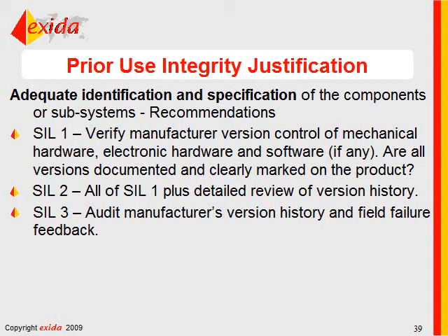What happens if you've been using a particular product for 5 years and you've got 1,000 of them out in the field and they've really worked well? And you've done good record keeping and you know they've worked well and they seem to be a prime candidate for prior use justification. And what happens if the manufacturer redesigns the whole thing and puts in all new software between then and now? I think your experience is basically wiped out or partially wiped out.